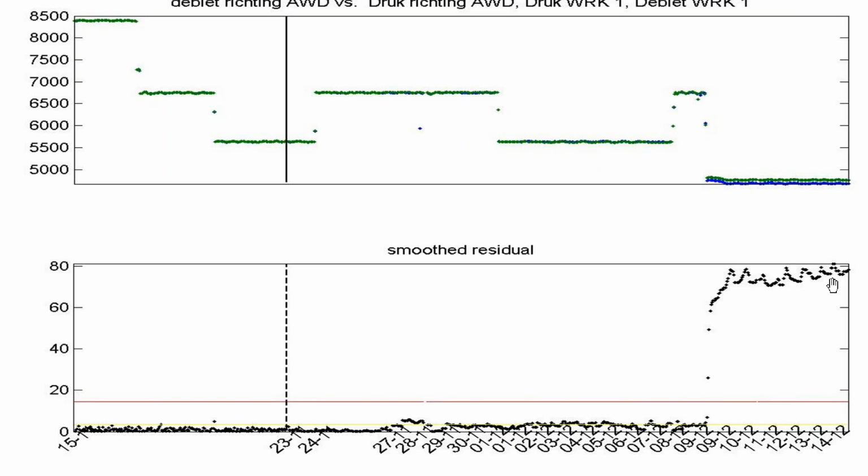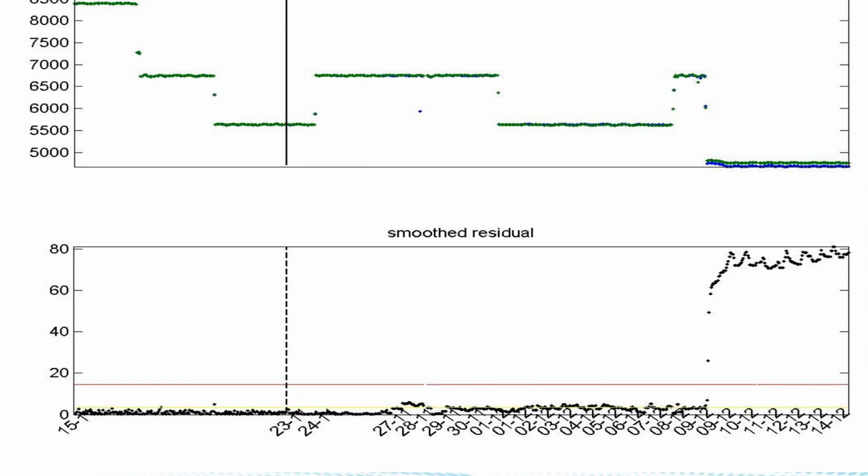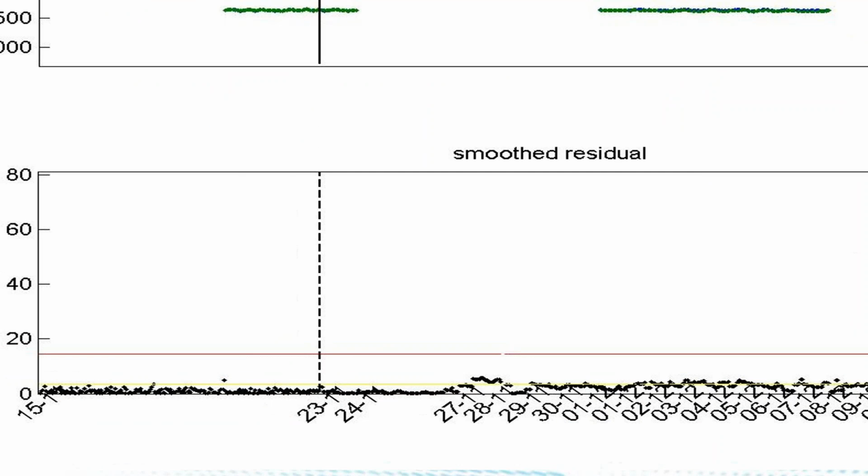And this is probably why they missed it, all 3 leakage detection systems they have, because it's a rather small leak. It ruined someone else's yard, but in terms of water companies, it's not that much. So in order to determine a defect and to differentiate it and to track its escalation, we have 2 thresholds. So the yellow threshold is basically the first one. We set it at 8, meaning 0.01% change.